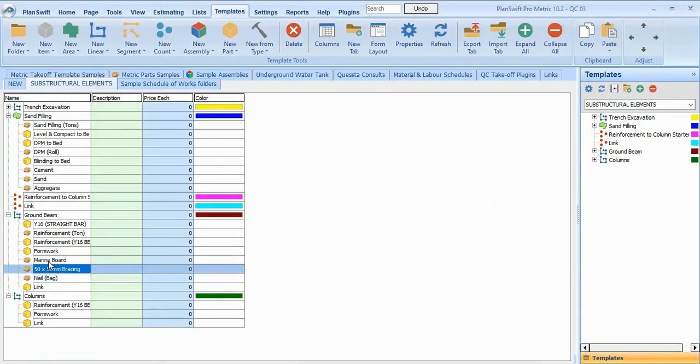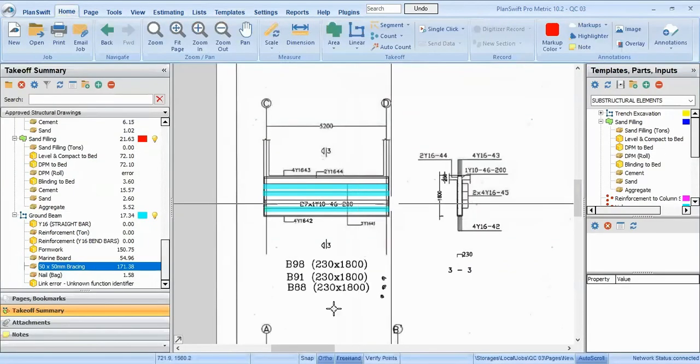Since we have knowledge of how to do material schedule for formwork, concrete, reinforcement, DPM, sand filling, I believe we can use this knowledge to develop other materials. When we start training on superstructural work, we do the same for all those elements too. So I want you to ask questions if you have any before we close.